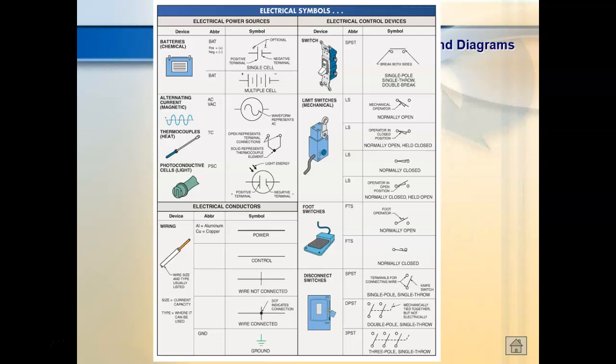These create a voltage that's proportional to the temperature that they're measuring. They're very accurate. The problem is they're not really fast. But these work real well in ovens and stuff like that because those don't heat up real fast, right? Water heaters sometimes use these. If you have a gas water heater, they do use the thermocouple to sense when the pilot light is on before it turns on your main gas valve.